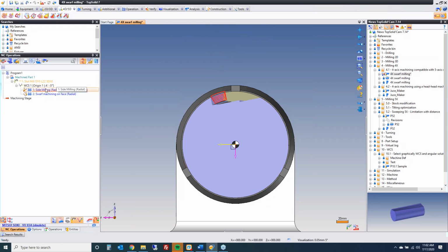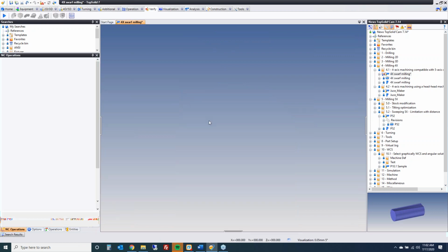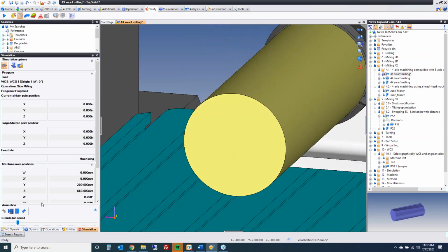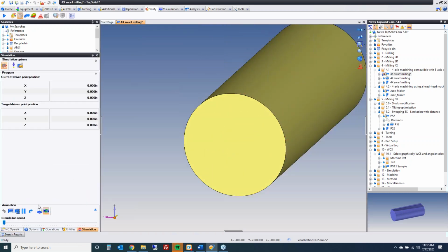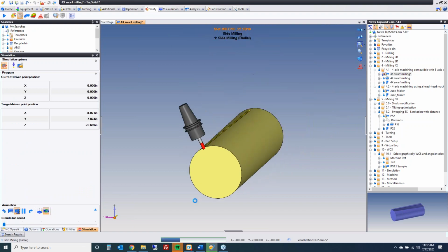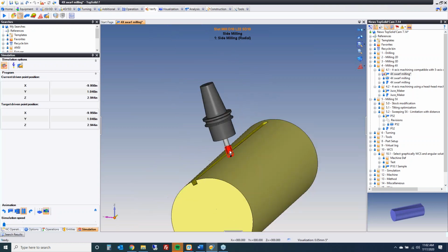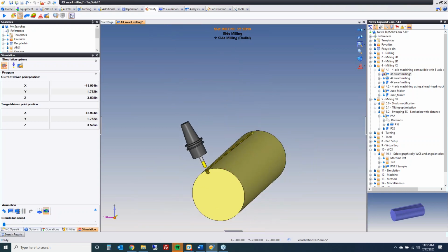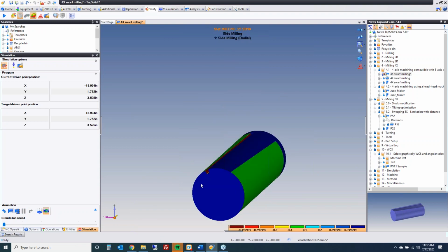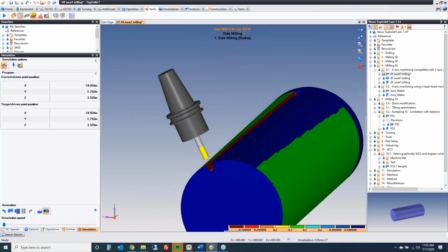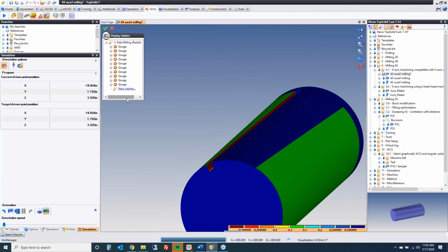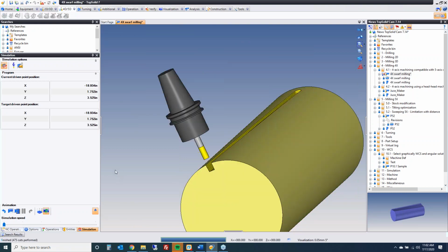If we go look at the toolpath and verify, just to have a quick peek at them, again, we'll go into here, and I'm going to do this without simulation just to win some time, right? And we'll hit play. Here you can see it's telling us we're violating the part. We have lots of collisions. If we go here and run a comparison, of course, we're going to see that blood red color. You can list all the gouges if you want, but you saw in the other simulation anyways that the tool just can't reach there because it's 4-axis radial.